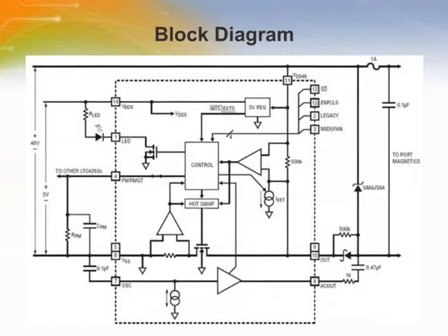The device connects to the signal transformers that interface the PSE to the Ethernet cable. It performs detection and classification of the device at the opposite end of the cable. And if this device is a powered device, PD, then 48 volts is supplied to its front-end power supply. The front-end supply of the PD then outputs an isolated voltage for use by the main load.